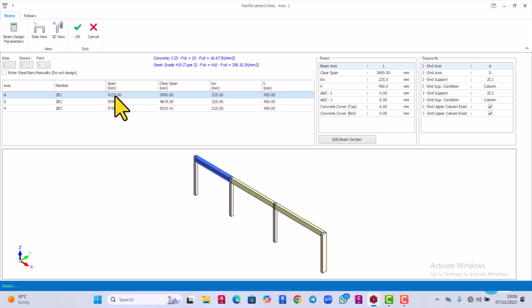So then when you look at this, there's always what we call the factor of safety in every design. Like you specified a concrete grade of 25 megapascal, you don't expect them to use the 25 in the design, because it is very much assured that on site they might have something higher than 25, and at the same time, after casting, when you check the compressive strength of that concrete, you might see that it will not be 25 as specified by the structural engineer.